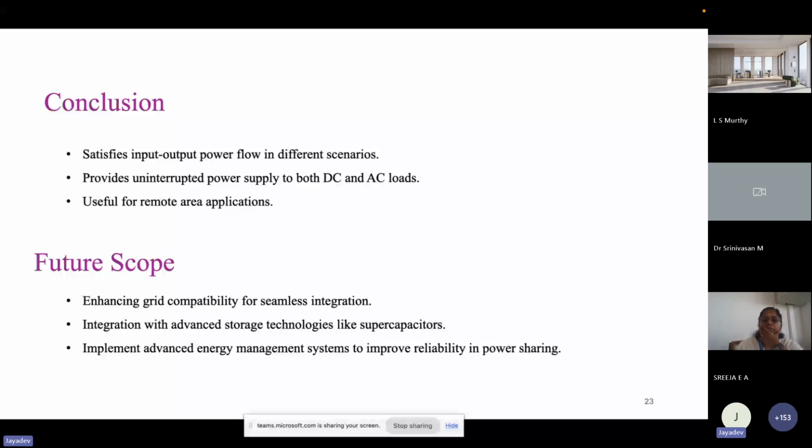We are using a C2000 microcontroller here, the F28379D version, and it has many EPWM output pins available. So you can supply as many as needed to both converters from the same controller. Okay, sir. Please send that when you're free.